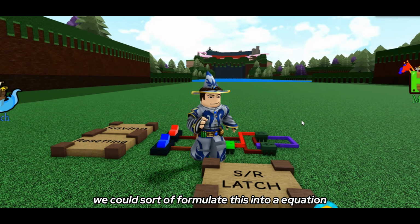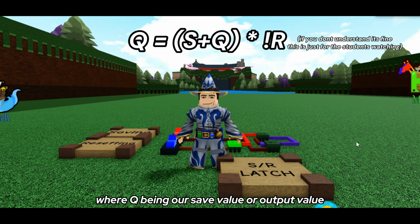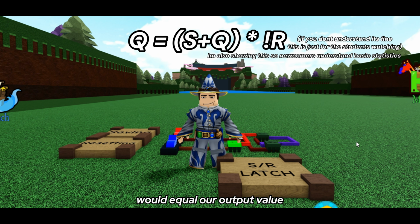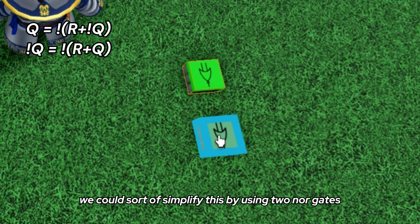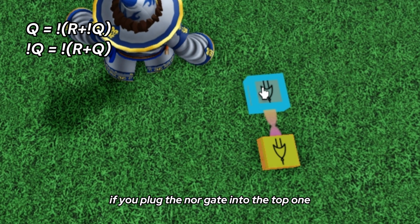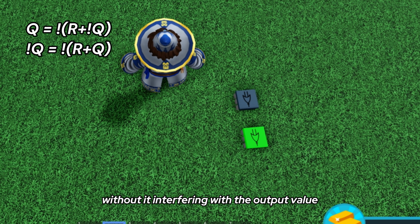We could sort of formulate this into an equation where Q, being our save value or output value, equals S or Q, and not reset. The Q would be plugged into itself, of course, in this situation. We could sort of simplify this by using two NOR gates. If you see here, if you plug the NOR gate into the top one, then it would turn it off. This would allow us to loop it back down without it interfering with the output value.